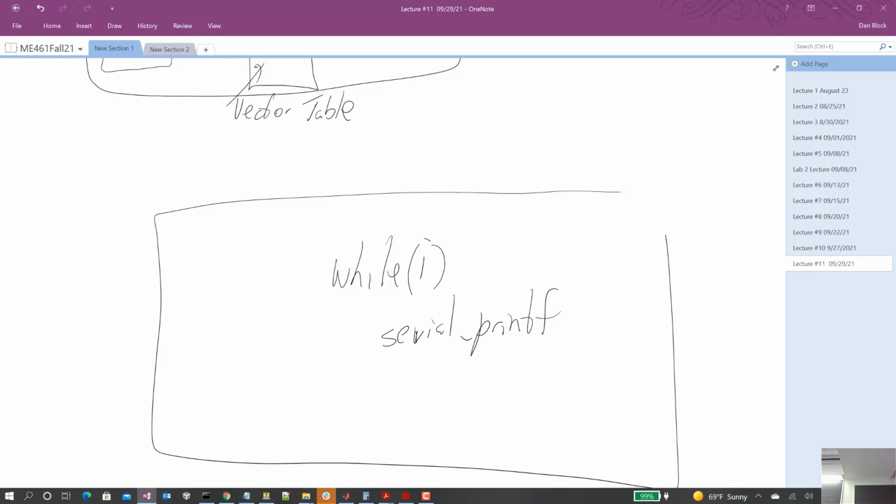So then the code over there doesn't feel like anything changed, did it? It's wherever it was, its state was saved. After the interrupt's done, it restores that state, and then you're back to doing the while loop. So that's how it can interrupt your lower priority code.